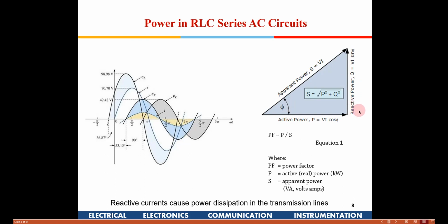So there are some compensation techniques available, where if there are huge inductors connected, then to compensate that you need to connect a few capacitors also. If you have huge motors and all, they offer very large inductance, and they spoil your power factor. So in those cases capacitors are used to try and bring the reactive power as low as possible. So that is done in practical applications.